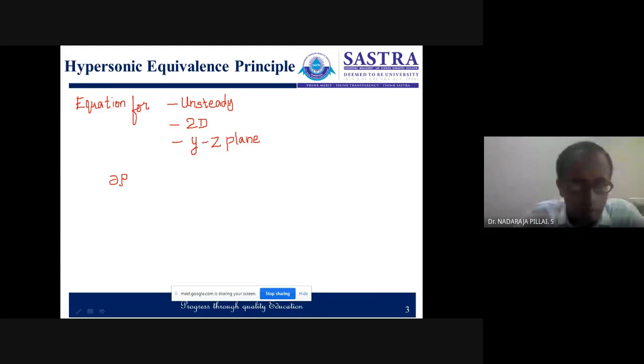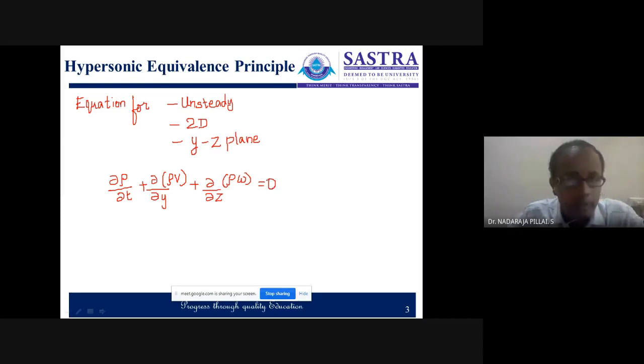So here I can write dou rho by dou t. So please note it is unsteady, right? Then dou by dou x of, sorry, it is in the YZ plane. So it is in the YZ plane and hence it will become dou by dou y of rho v plus dou by dou z of rho w, that is equal to 0.